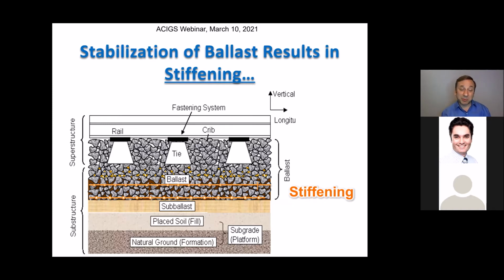Well, because especially ballasted track gets a lot of maintenance with tamping tines, right? The geometry corrections, and railroaders want to do that often. So you want to put the geogrid, in this case, far away from the reach of those tamping tines. And that's typically for our concrete sleepers or ties, in our case, at least 8 inches or 20 centimeters below the bottom of the tie, is where you should place your geosynthetic or geogrid material. But typically towards the bottom also works.